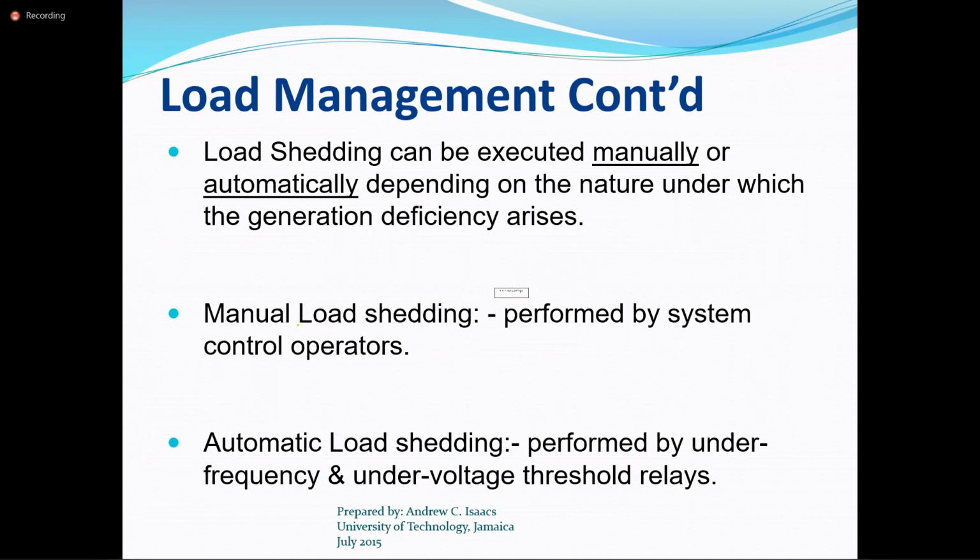However, you can have automatic load shedding. And these will be based on the frequency or on the voltage threshold release, because a dip in the voltage or a drop in the frequency is an indication that the load is higher than the generation. And once you have that imbalance in terms of frequency, then the generator is also set to pull from the system.